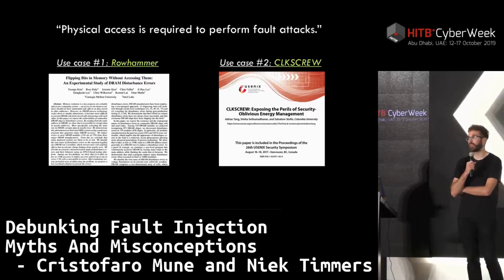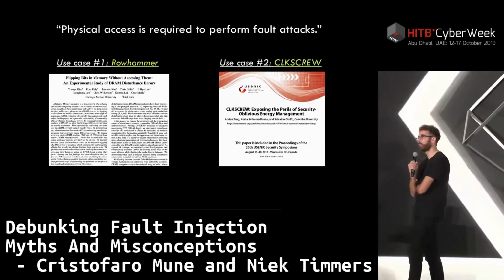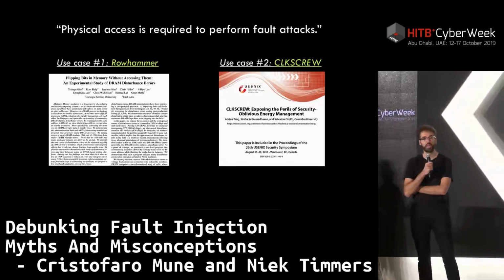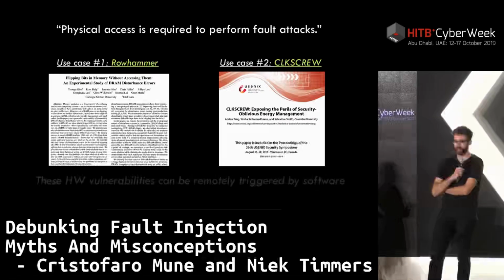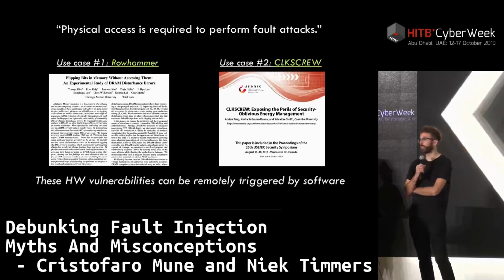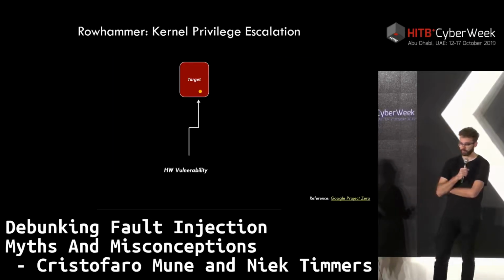So you're running either the chip too fast with too low a voltage or the other way around, but it allows you to make the circuit within the chip misbehave in a similar fashion as you would shoot a laser on the chip. So the key point here is that these hardware vulnerabilities are triggered by software, and this means that you can trigger these vulnerabilities remotely. So you do not need physical access.